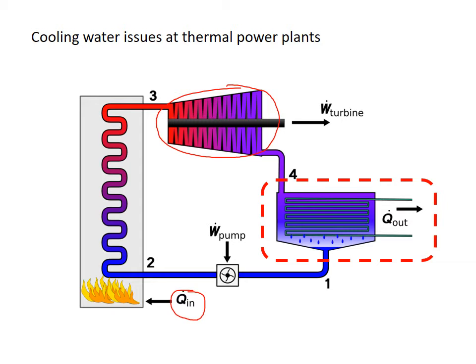And it's cooled down using some sort of condenser coil here, which is this squiggly teal line going back and forth here. And through this condenser coil is being passed cold water that was drawn directly from a river or a lake. And so that river or lake absorbs a lot of the heat from the steam and then is sent back out of the power plant, either into a cooling tower where it cools down through evaporation, or it's discharged directly back into a river or lake.